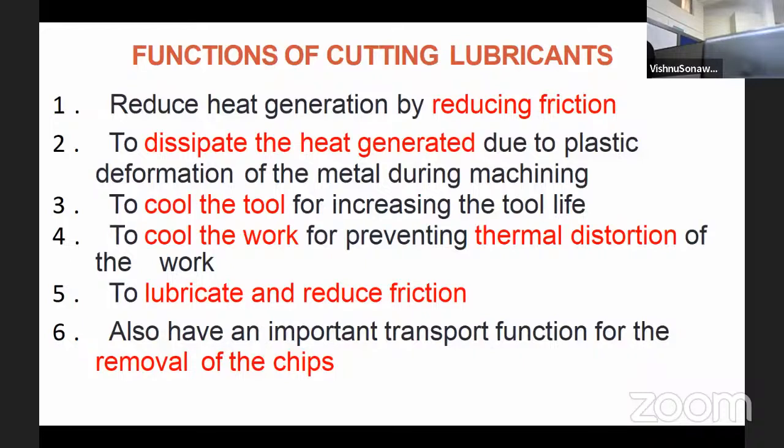In forging operations, rolling operations, metal forming and mold design, this plastic deformation technique is tested, and we have to supply the proper amount of coolant at the interface of the cutting tool and the workpiece to increase the cutting tool life, and to cool the work to prevent thermal distortion.